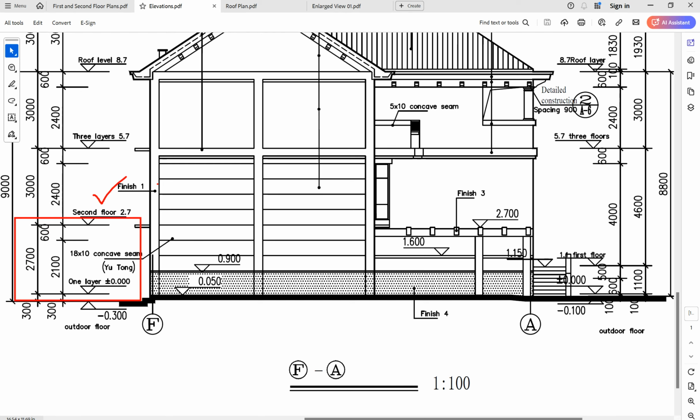Okay, so I go back to Revit, and then to make it 2.7, I actually no need to create this dimension. I will show you this. When I click here, this is here got the level, okay? So I can put 2700, click outside, then it will show. Actually, it's already 2.7 accidentally. I'm not magic. I just draw one line, but it happens 2.7.